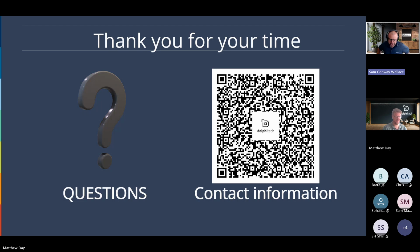Yes, you can map with ARCUS. So again, ARCUS is the post-processing. The way that you capture your data, whether it's encoded or manually stitched, still remains exactly the same. Once you've captured your data and saved that FMC file, it's at that point that you would apply ARCUS. If you've got a relatively large area, you wouldn't need to apply ARCUS to the whole mapped area. You could just focus on one particular area where you suspect or can see the flaw, crop that data out, and run ARCUS on the smaller area rather than the total area.